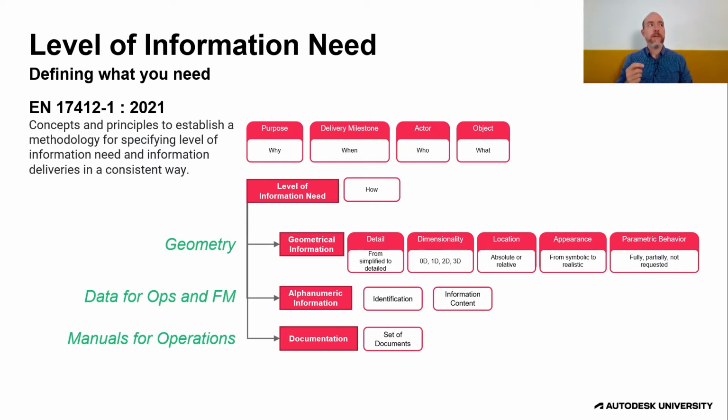Now, there are other standards that go on to explain how this could be done. As an example, EN 17412 Part 1 goes beyond that and looks at how you define things on the level of geometry, how you define them for data operations and facilities management, and what manuals and documents are needed. You might say, well, wait a second, what do you mean geometry? That's just LOD, right? No, because you might ask how accurate is it? Is its location correct? Is there a visualization being produced?